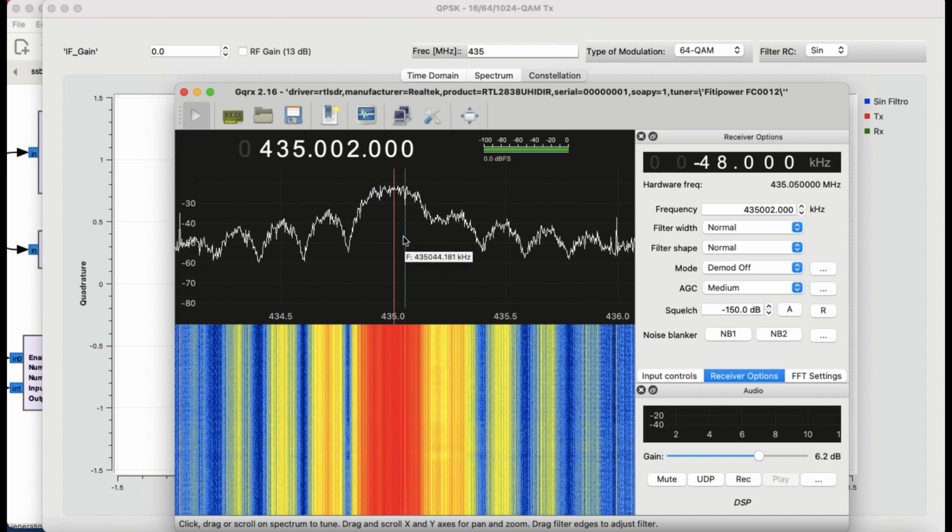The reason is that when you're close to the base station, adaptive modulation and coding, which is used in 4G and 5G, allows you to have higher data rates. When you're further away, you will use a lower modulation scheme. So you will still get data services, but not as fast as when you're using 1024 QAM. So that's the basic idea behind these modulation schemes.